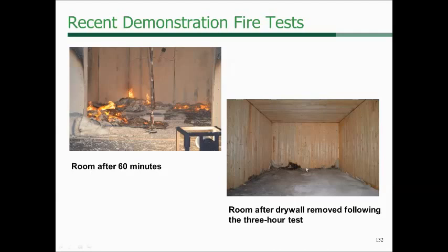I think I have a close-up. No, I don't have a close-up. But there was a little bit of charring here. You could actually go in and touch the cross-laminated timber, and it was cool to the touch. So quite a bit of fire resistance is provided.